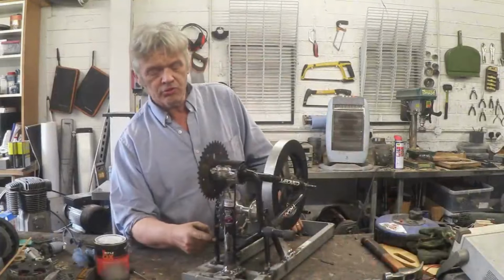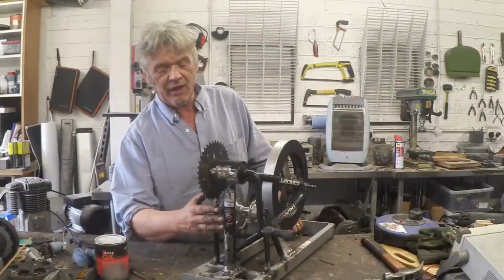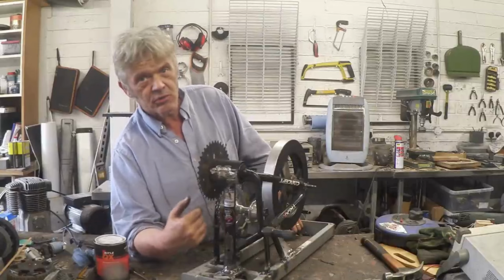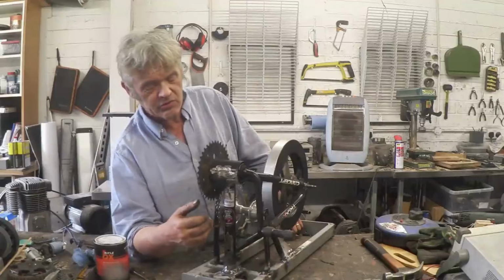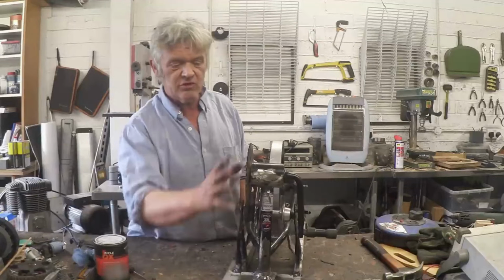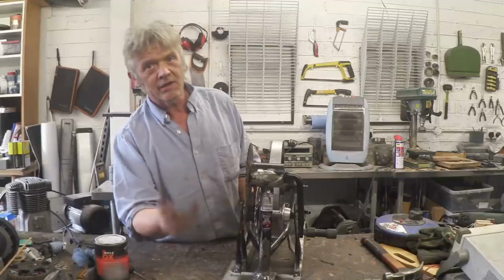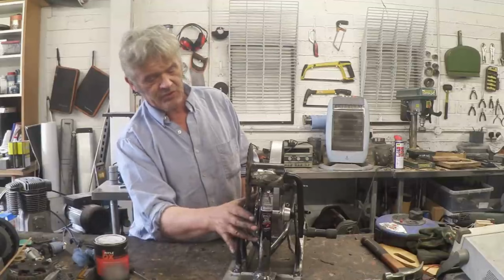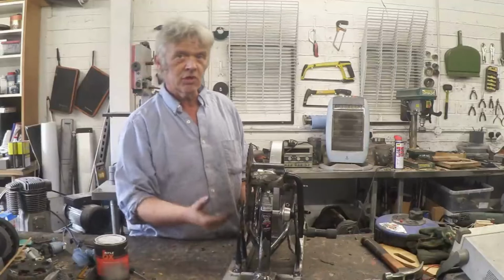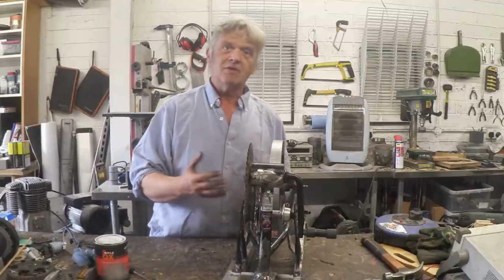So welding in a couple more dropouts means I've been able to put that in there. Now all I did to swap those cogs around was unscrew it and swap the cogs, using the spacers, bolt it back together into those dropouts. So when I put a chain between this one and the small cog here, I'll get a 2.5 to 1. And then from this big cog here to the actual drive cog, I'll get another 2 to 1. So instead of being 2 to 1, it's now about 5 to 1.